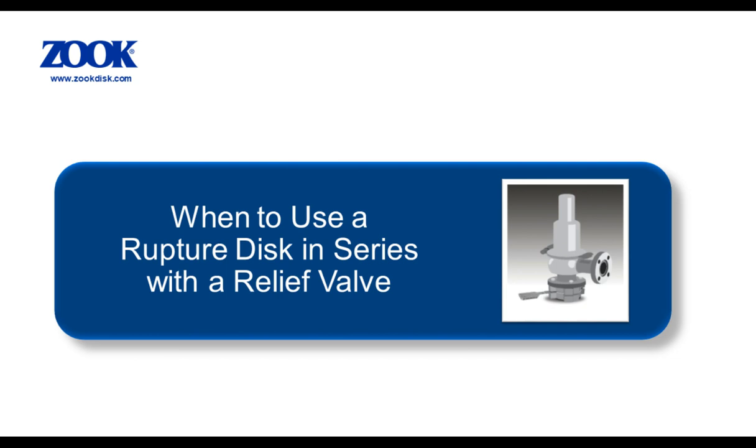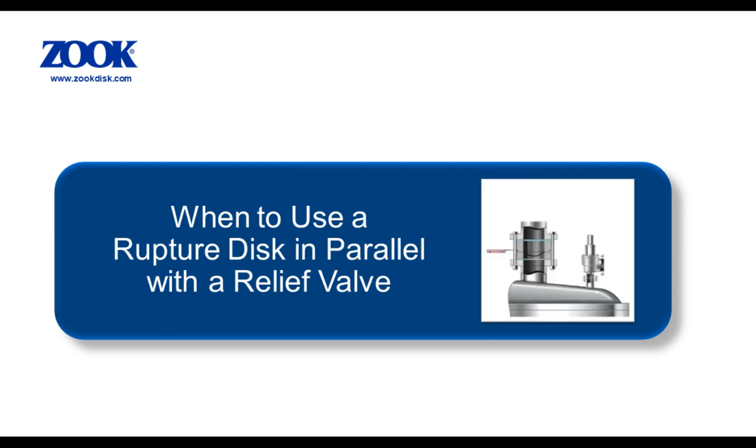There are, however, sizing-related challenges when combining the two types of pressure relief device that always need to be considered, and we will address them when we touch on sizing later on in the presentation. And because a rupture disc is a differential pressure relieving device, pressure cannot be allowed to develop in the space between combination devices, and a pressure gauge, tricock, free vent or suitable telltale indicator should be installed to ensure pressure buildup downstream of the disc is detected and eliminated.